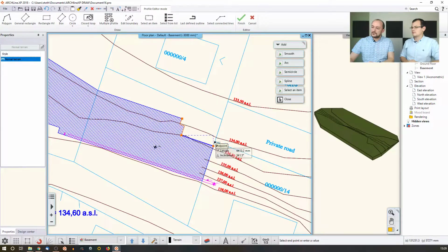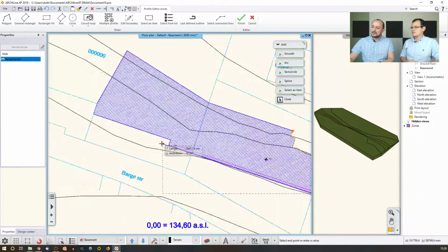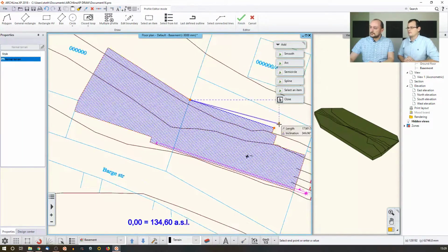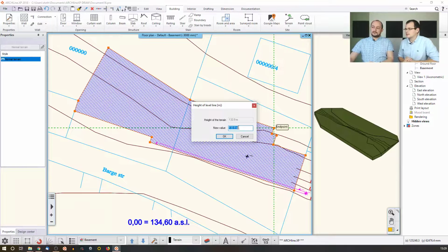I can also select this area. I just would like to quickly sketch this same contour. And then when I'm done, what do you do next? Now I have to tell where this flat ground is measured from the sea level. This is why the engineer told that 0.0, this is where this area will be, is at this specific elevation. So I just use the same elevation.